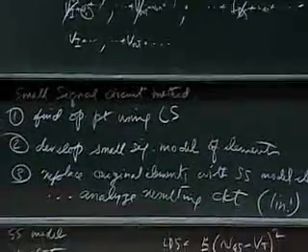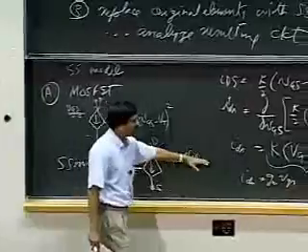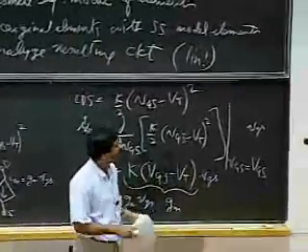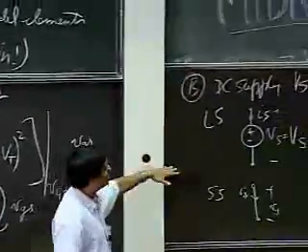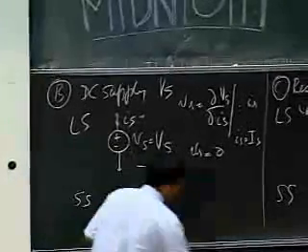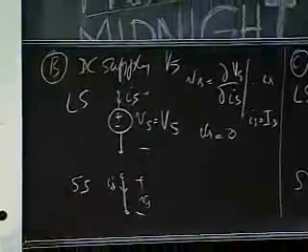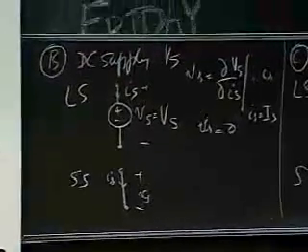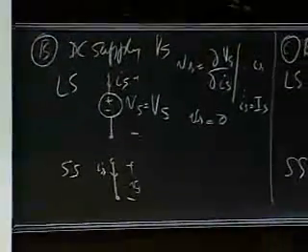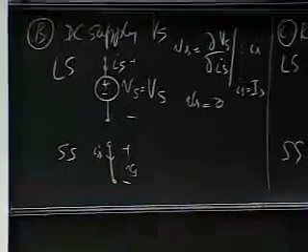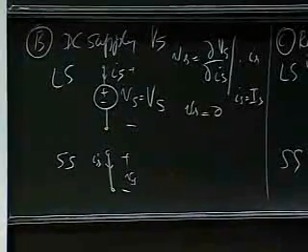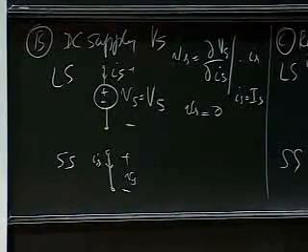For the nonlinear MOSFET, the small signal model was a linear dependent current source. For a voltage source, the corresponding small signal model was a short circuit. Okay, and that makes sense intuitively. If I change the current through a voltage source by a small amount, by how much does the voltage change? It's a voltage source, silly.